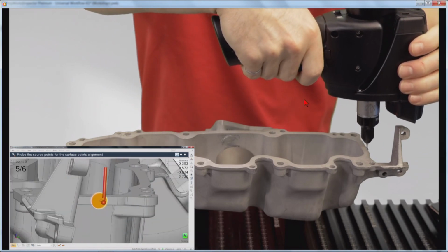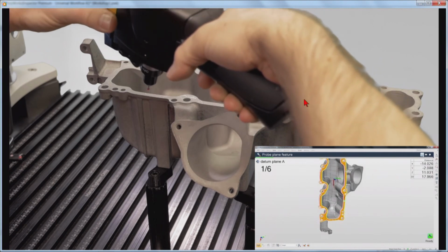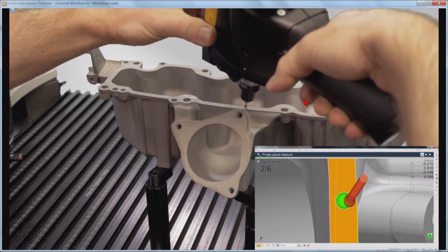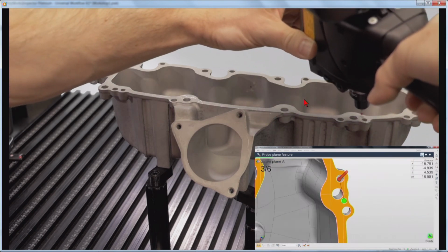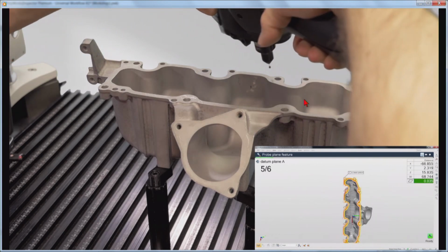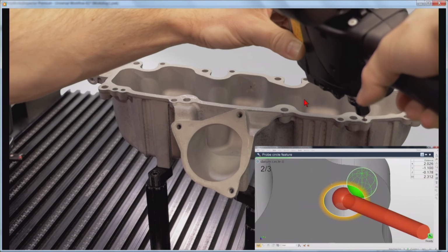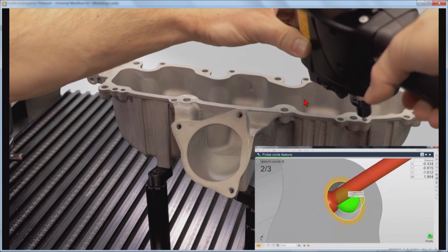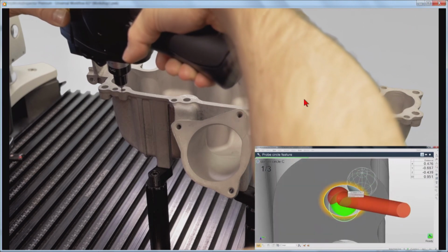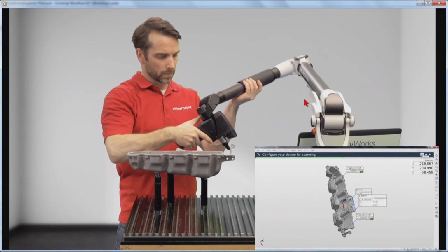And from there, we will proceed by measuring our datum plane A with the 6 points we wanted to use for guidance. So the operator can try to hit approximately the points where they are shown on screen. Now, once this is over, you can see that you cannot make any mistakes while probing datum circle B and C, as you can see the orange probe that hovers around the right hole, which means that you're probing the